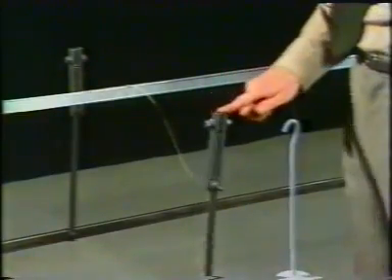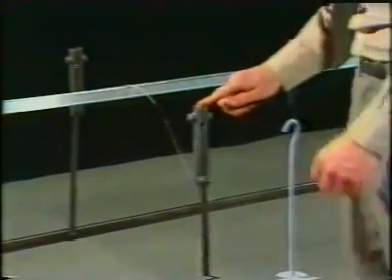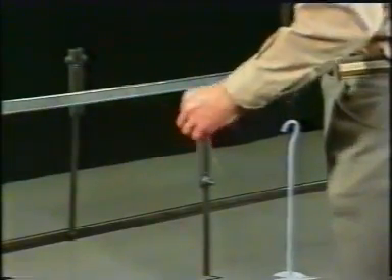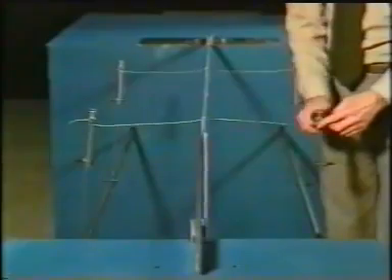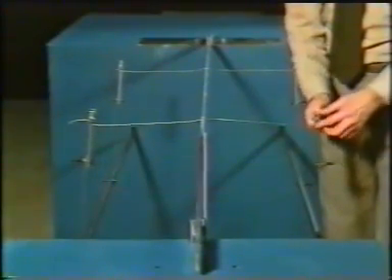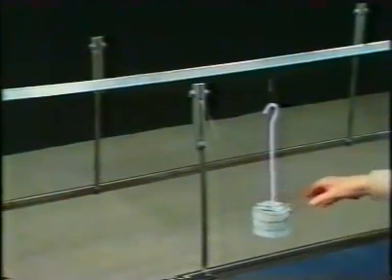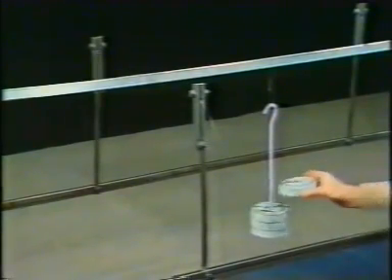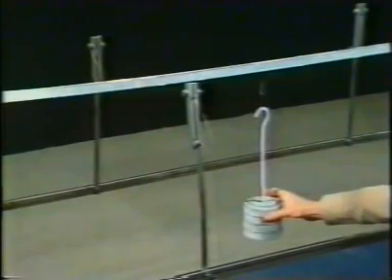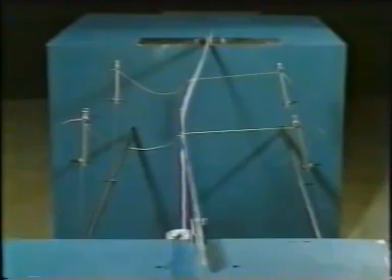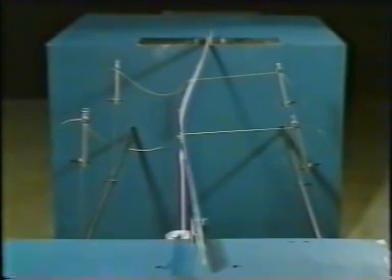In this example, although the bracing is very light, it has considerable axial stiffness. This stiffness is important. If the support for the bracing is less stiff, then, whilst the strength of the bracing remains the same, the effective restraint has been significantly reduced. Load is applied. And instability now occurs at an intermediate load, higher than that for the unbraced system, but well below that of the system with a very stiff bracing.